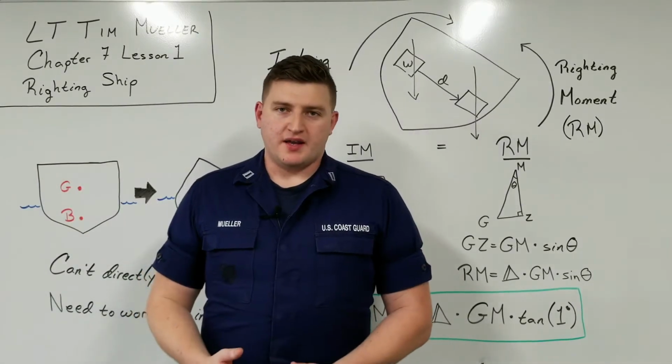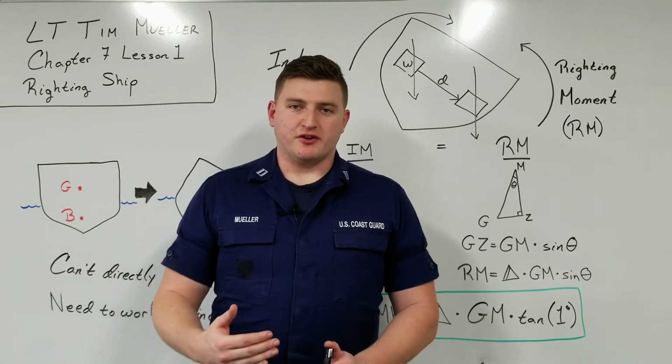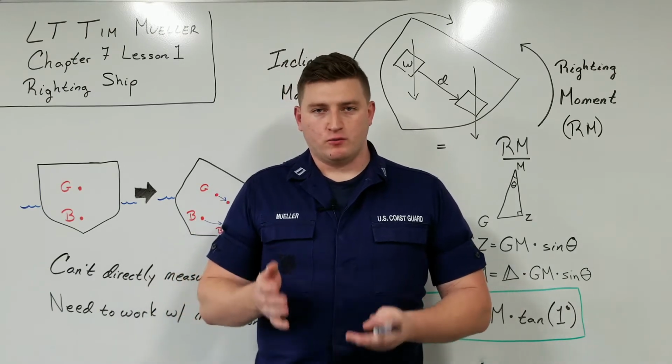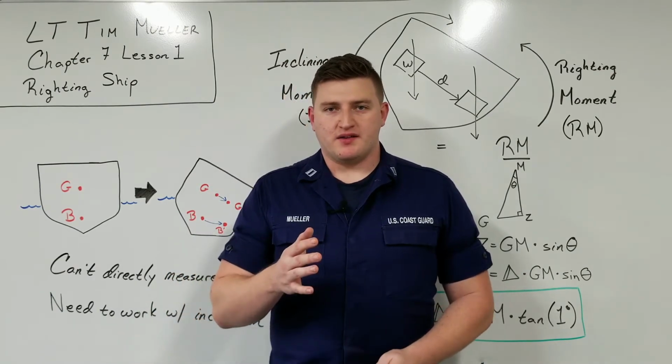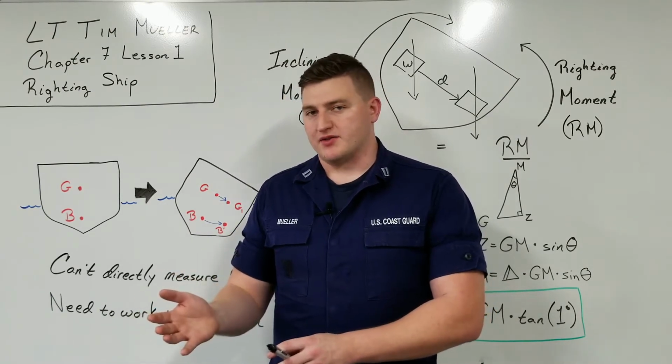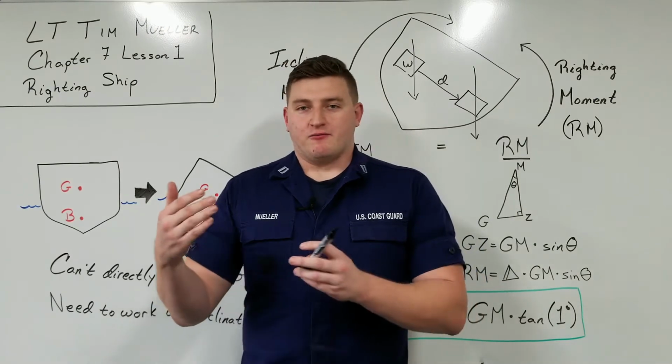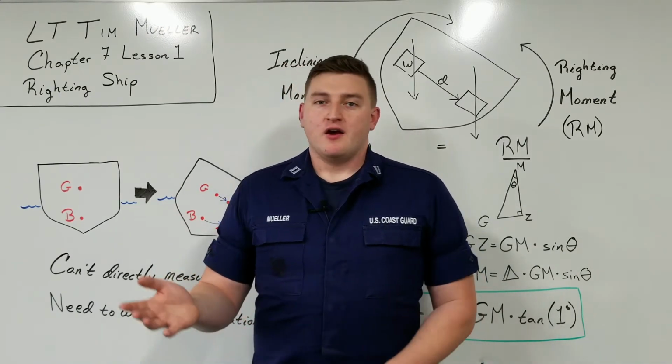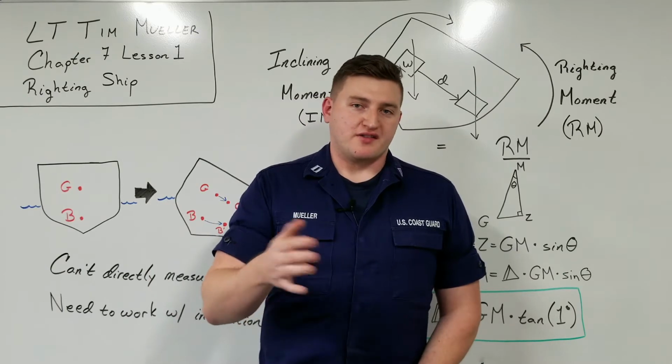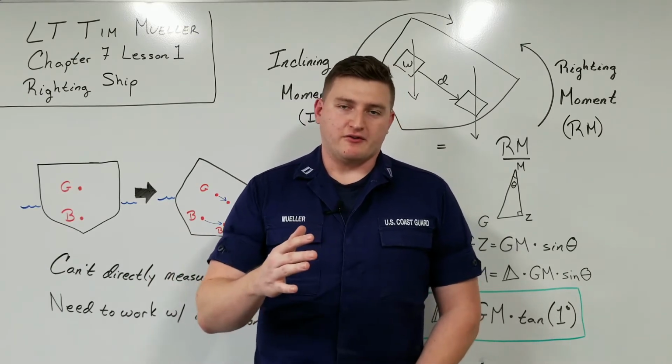Now, when we here at DK School refer to MH 1 degree, it's only that moment to heel 1 degree. If we have to correct a list, or if we're doing more than just the MH1 moment, then we know that we're going to go more than just 1 degree, or we're going to have to impart more of just that moment to correct more than 1 degree.